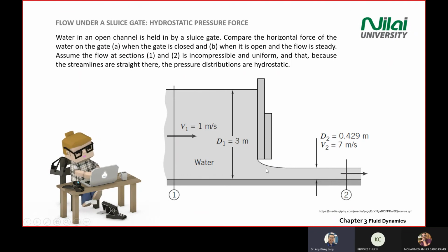If you stand here, what is the force that you feel when the door is open? And what happens if you close the gate? Because we are looking at a momentum equation, we deal with the velocity of the mass. Mass moving at a certain speed creates momentum. So we need two sets of calculation for this scenario, one for closed, one for open. We assume the flow is steady, and also we assume incompressible flow, and we have hydrostatic pressure in this case.